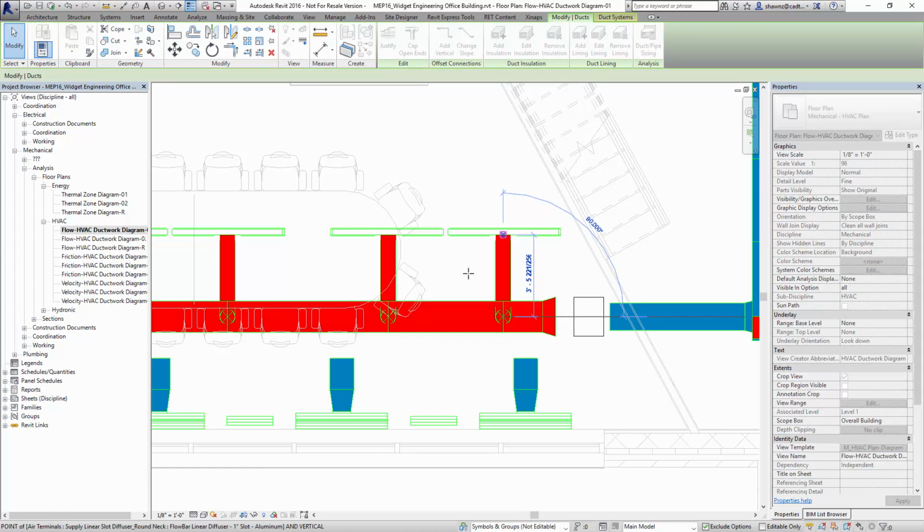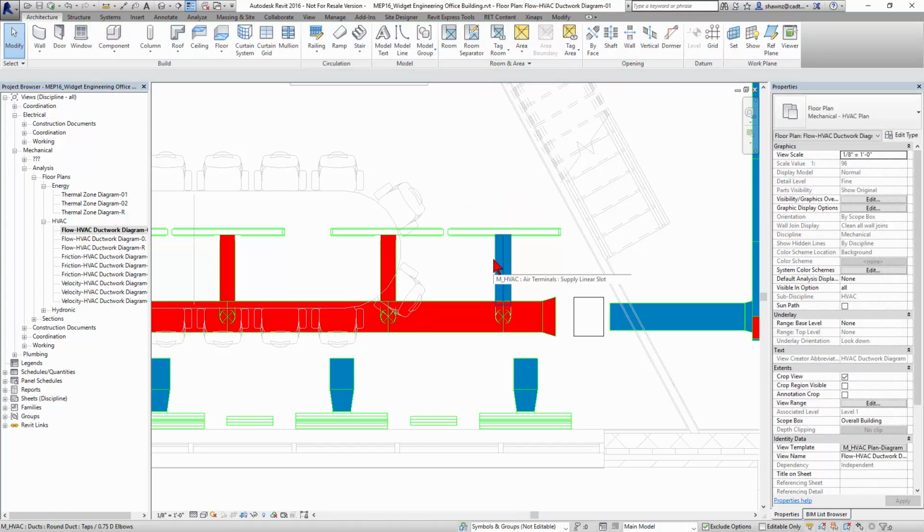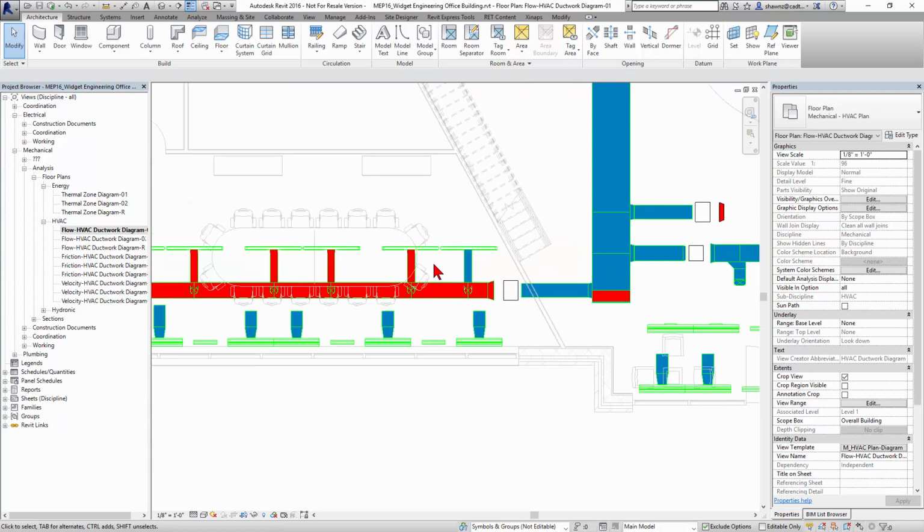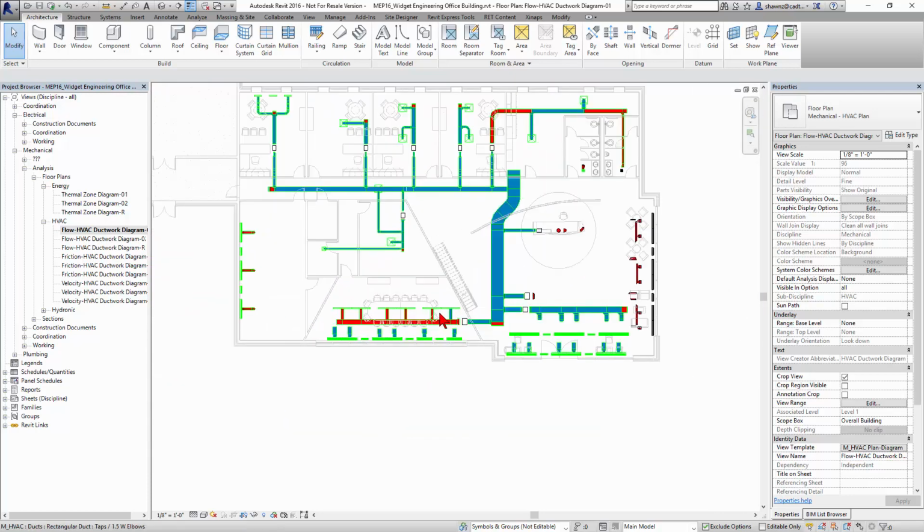But if they have flow, when I connect this up, you'll see that red duct right there will change to blue once it's actually receiving information from the air terminal. This helps you really quickly at a glance across your project look and go, where do I have problems? Where am I not getting proper airflow? So that when I click on the main duct, can I actually assume that the numbers that it's giving me for total flow is correct, or is it not correct?